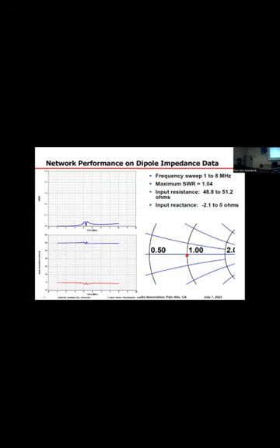And if I put it on the Smith chart, the impedance is that little dot very close to the center of the Smith chart. Isn't that interesting? And that's for a 100-foot dipole. Actually, you could go below 1 megahertz and you could go above 8 megahertz. I just graphed it from 1 to 8, but it works out of the band just fine. Okay, so this is just using constant resistance network theory to design the matching network for the antenna.